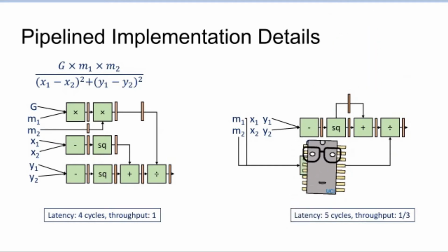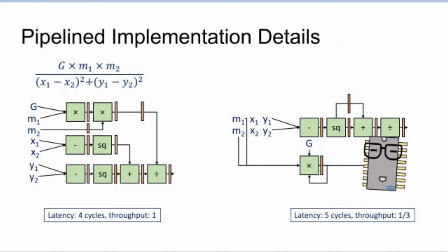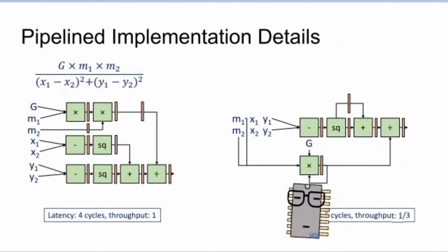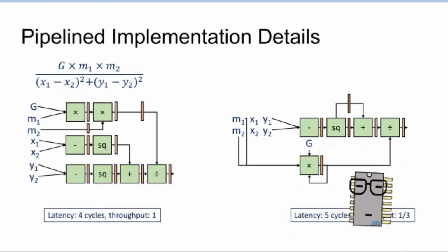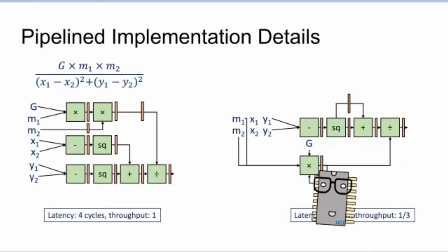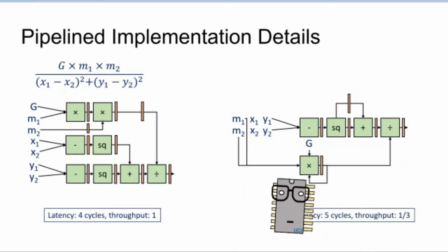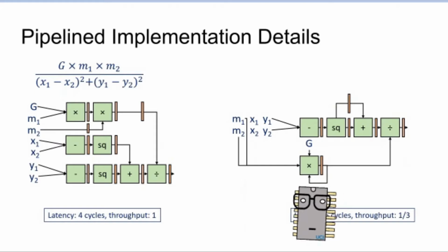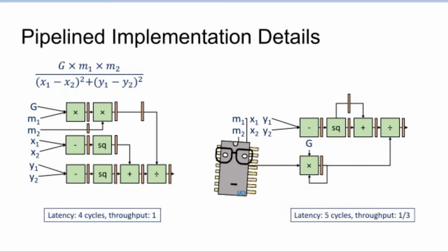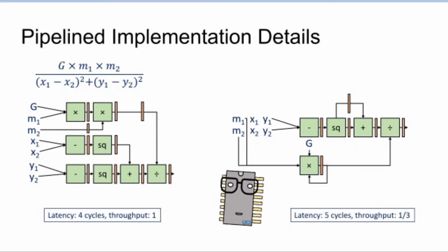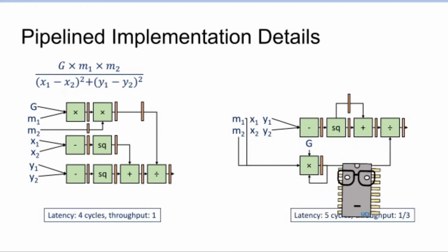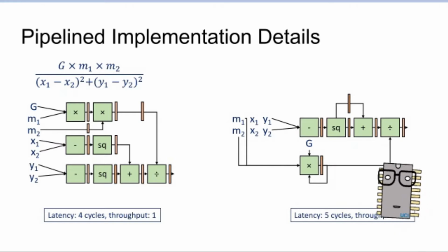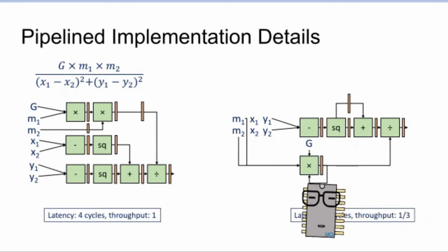Similarly, until this pipeline process completely finishes, this pipeline stage has to wait. So there has to be a correct number of pipeline registers here to match the latency. But thankfully, because there's also a loop here, and M1 and M2 are the last to come into the pipeline, 2 cycles later, only then will these pairs of data come into the pipeline, so the number of pipeline registers required is still small, just 1 actually.